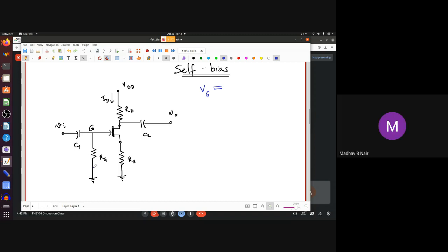Current into RG. What into RG? The current into RG, but how much should the current be? The current in this, where will it go? There's a capacitor blocking DC on this side. You can't have a current just hanging around. It has to go somewhere, right? It can't go this way. Where will it go? Can it go this way? Yes?